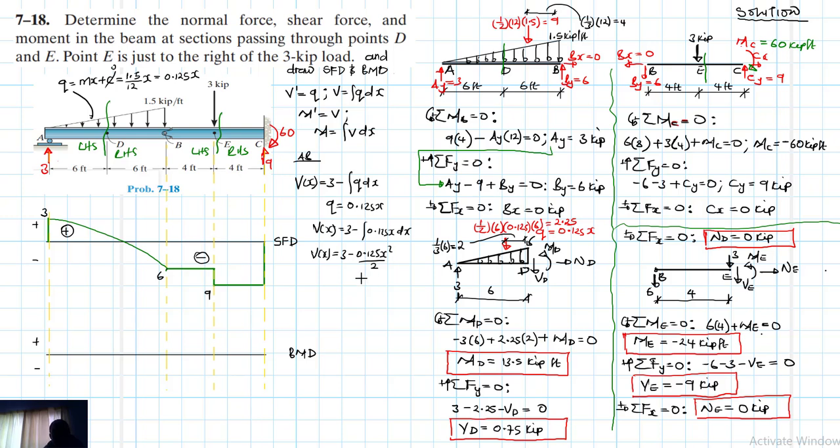And it's the same function we are going to use for finding this point here where our shear is equal to 0. We'll need to find this point later on for us to find the maximum value, right? Here shear is equal to 0. So we need to find this later on. We need this length, so that we come and find this point where we have maximum moment.